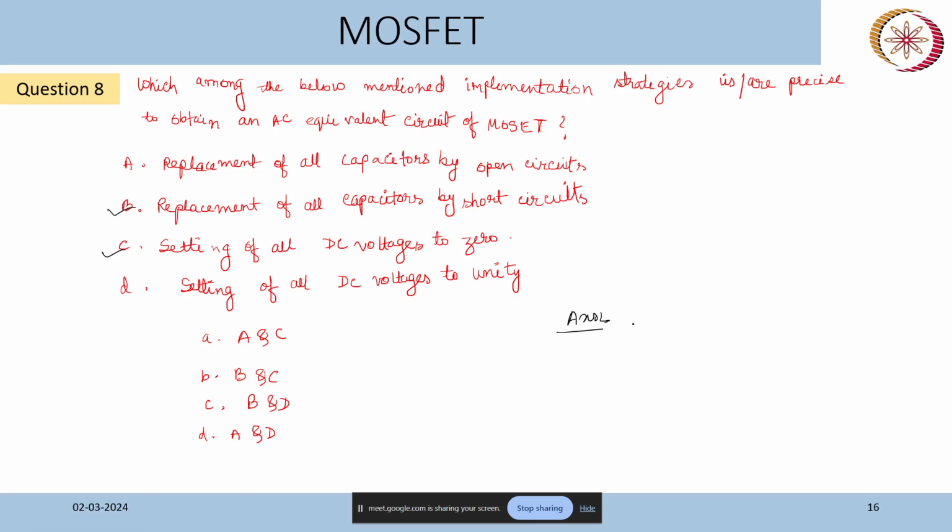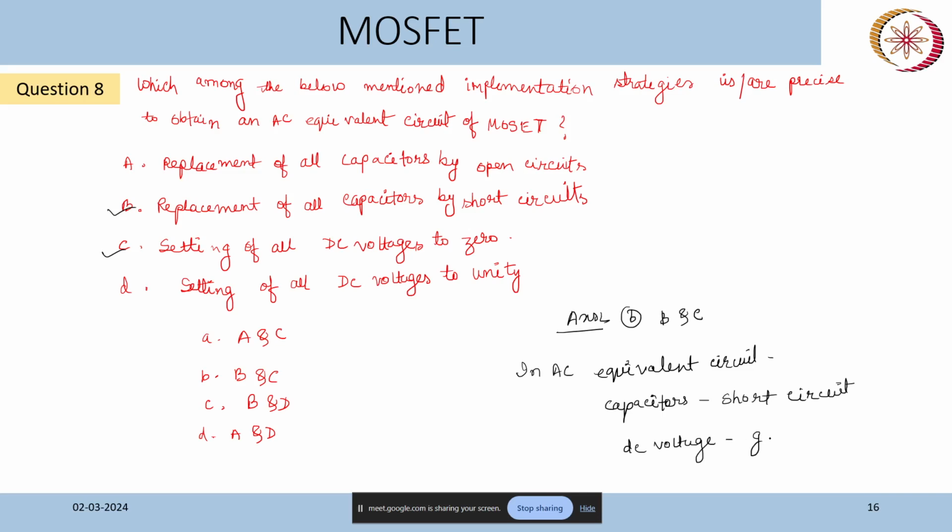So the answer is B and C. In AC equivalent circuit, capacitors are short circuit, and AC voltages are grounded. Okay, is that true for any device?